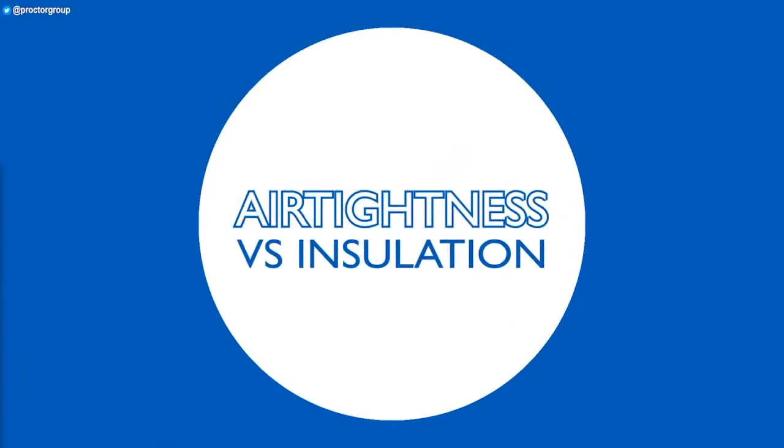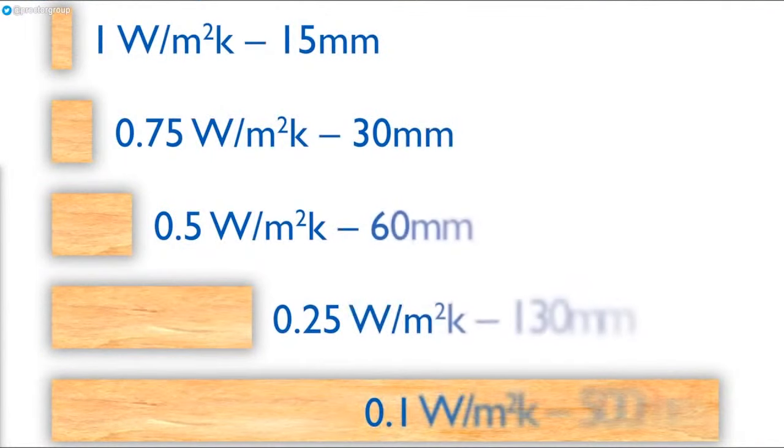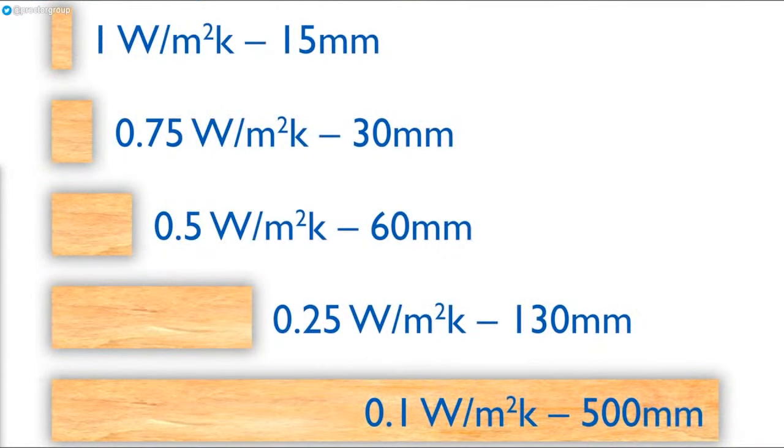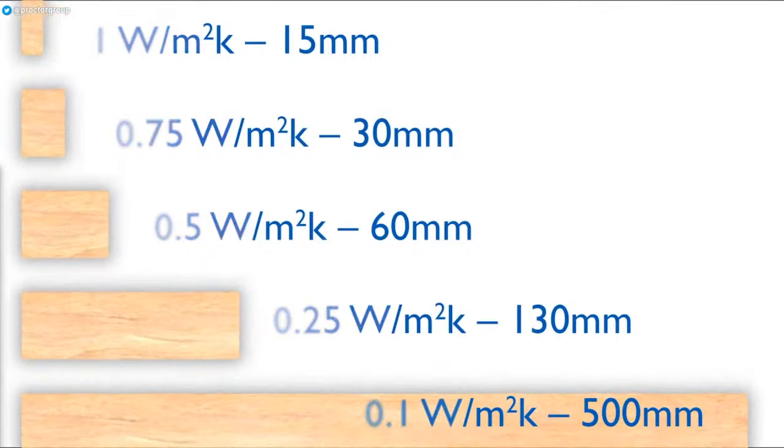While fabric insulation is effective in reducing heat loss from the building envelope, as insulation levels increase, its effectiveness per unit thickness begins to drop off. This is because the thermal transmittance, or U value, of a construction is the inverse of its thermal resistance. What this means in practice is that boosting insulation levels is only practical and cost-effective up to a point. Beyond that point, we need to consider alternative measures to restrict heat loss from buildings.